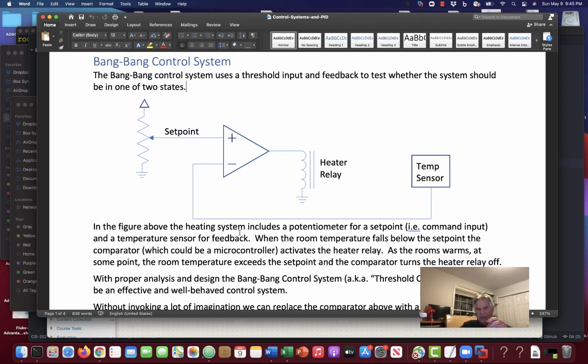In other words, you have to go above 2/3 of the supply voltage to put the flip-flop in one state, and then you have to go back below 1/3 of the supply voltage to put the flip-flop back in the other state. And if you use capacitors and resistors, this is how you can build astable multivibrators, that is, kind of oscillators, free-running oscillators.